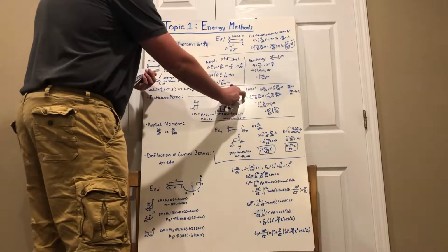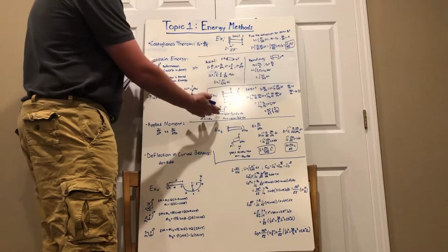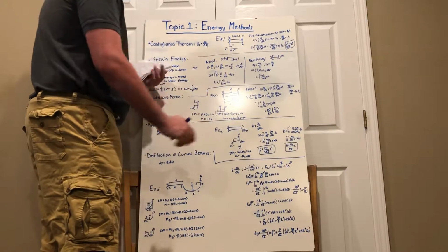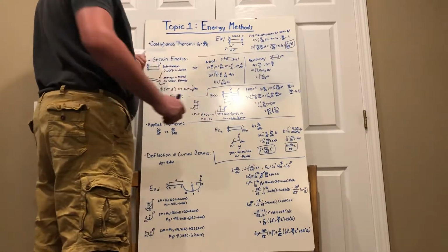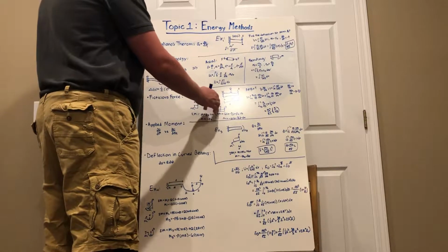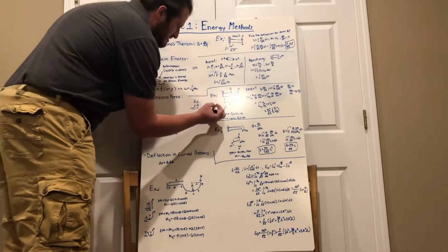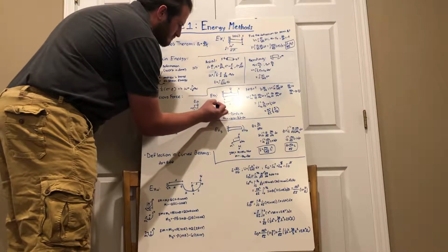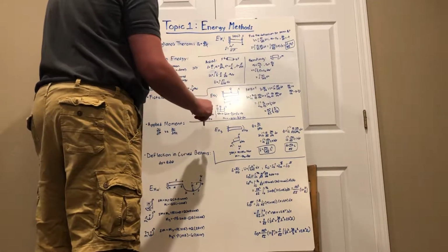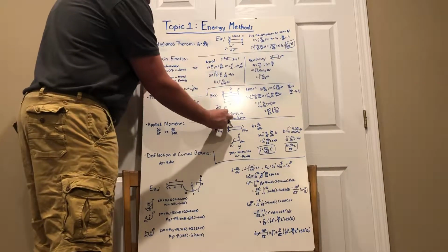I'd like to extend this to where we have our cut on this side of the fictitious force, right? So we're going to sum the moments again, in a similar process, where we'll have an M here, Q, and P this time. So what are we going to do? Our sum of moments is going to equal M plus the Q, this force here, times x. This time our x is going to be this distance from this force here. That's going to be our x. Ooh, sorry. And this entire thing has its length L. So we need to add this portion to it that we're not measuring from.